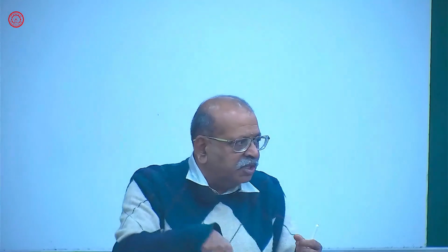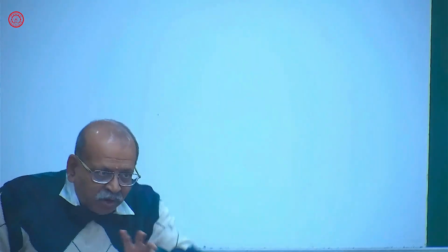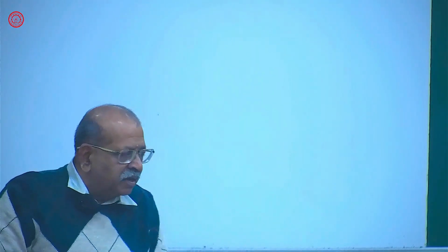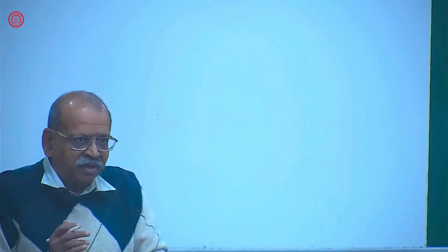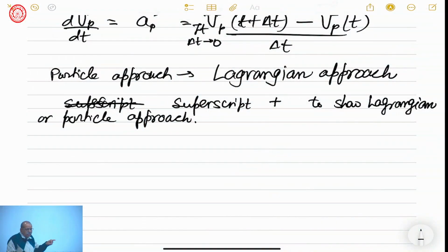We are able to study a rigid body as a system of particles because when we combine all these particles, there is some law which governs their acceleration together and their angular acceleration together, by Euler's first and second axioms. But in fluid mechanics, the fluid is no longer a rigid body, so particles can move on their own. So if we want to study a Lagrangian approach, we have to label the particle.